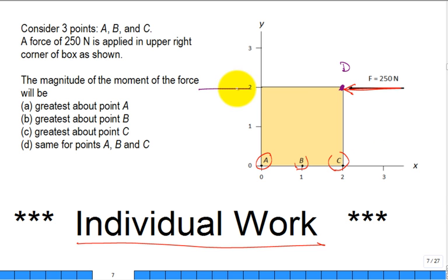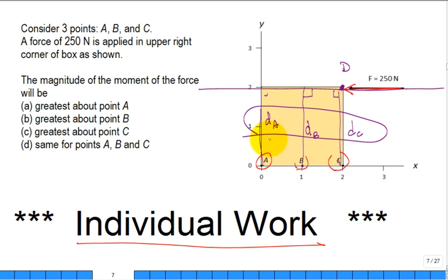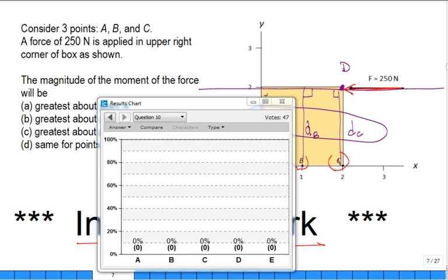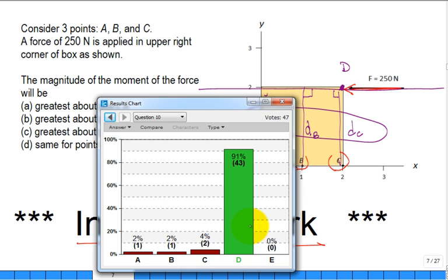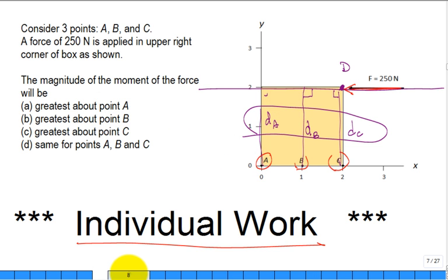It's the line of application going through the point of application of the F. And then you would say, what's the minimum moment arm distance? That would be that distance for going to C. It would be that distance for going to B. It would be that distance for going to A. And what about these moment arm distances? They are the same, so this is the case where most of us were on top, right? It's the same. All right, let's press forward.